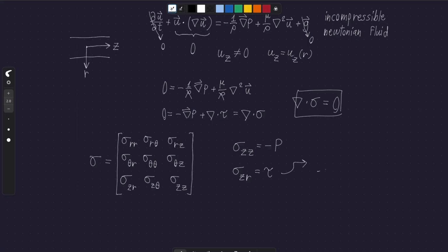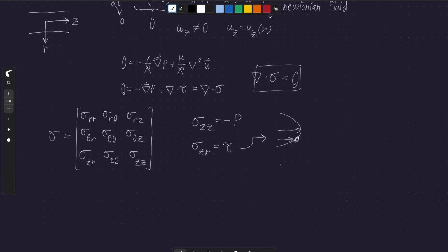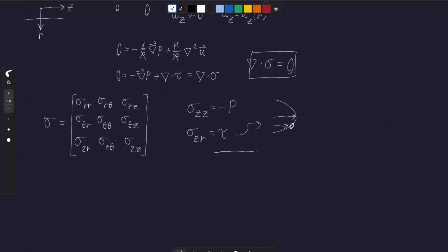When the fluid is going at different speeds in the pipe, this creates a shear force. So you would have something that looks a bit like this. Here's your pipe. Here's the velocity profile, u. There's a condition that on the edges of the pipe the fluid is not moving.